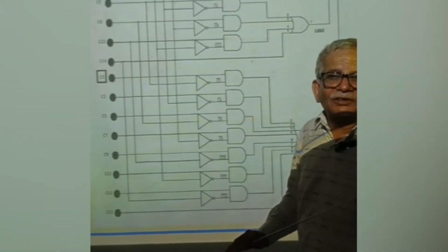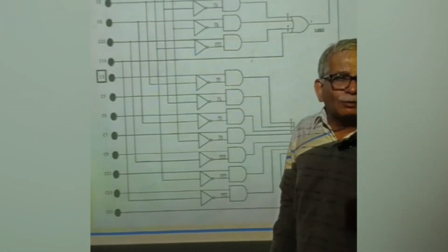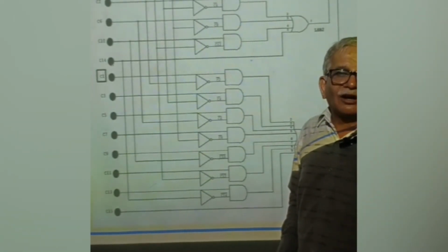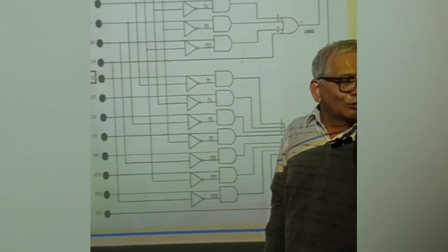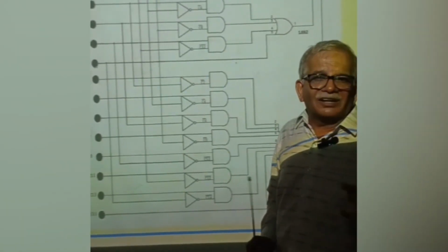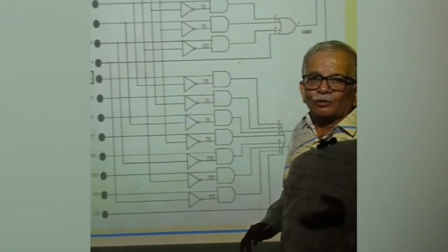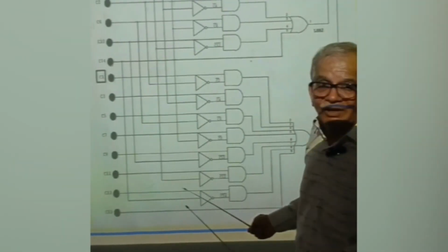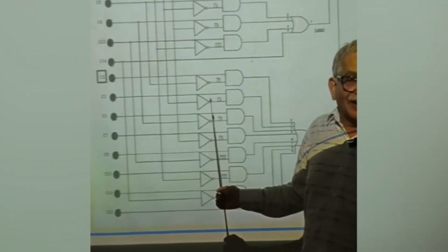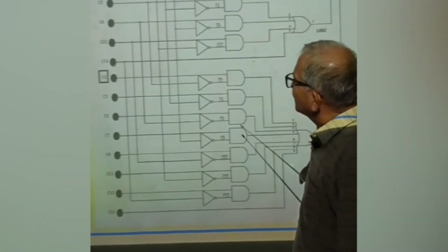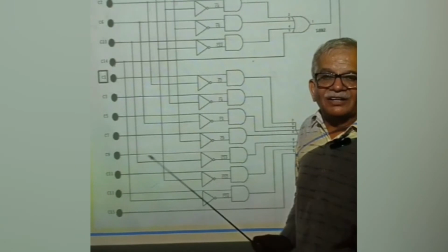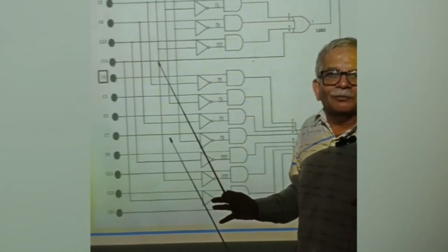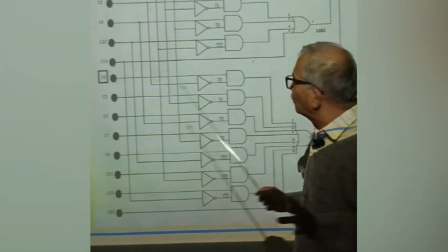In the manufacturing process, when millions of things are made, it is easier to work with one single thing. So we always use NOR or NAND gates, which are called universal gates. Using those gates, we can produce anything else. So when you go for mass manufacturing, you will not use different kinds of gates. These are just schematic diagrams. Actually, you can use these different gates and make the circuitry, but it will be very complicated. It is very difficult to make this circuit, and it will be very difficult to work also.